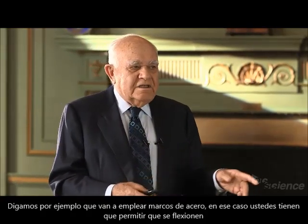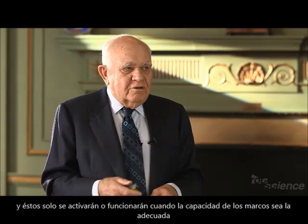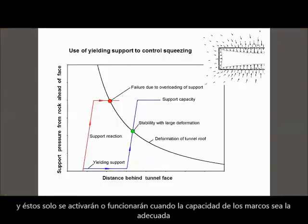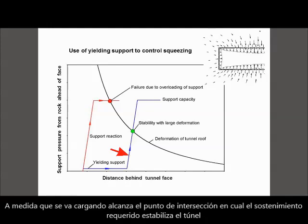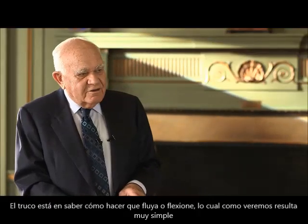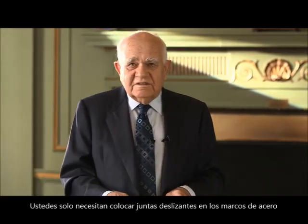So what you do is you put the support in a rudimentary form of, let's say, steel sets, but you allow it to yield, and it is only activated when you are sure that its capacity will be adequate. So the blue line here is a yielding support system which kicks in perhaps 15 meters behind the face, and as it picks up the load, it reaches the intersection with the required support line and stabilizes the tunnel. The trick is, how do you allow it to yield? And it turns out to be very simple. You just put sliding joints in the steel sets.